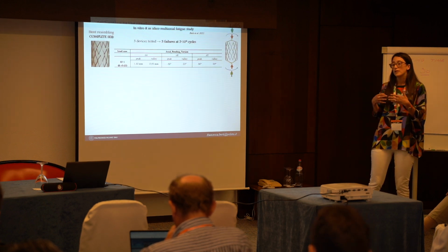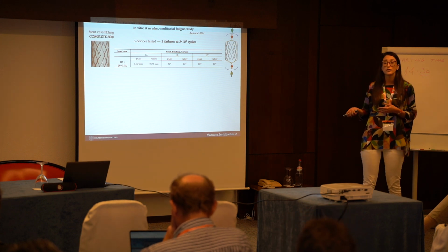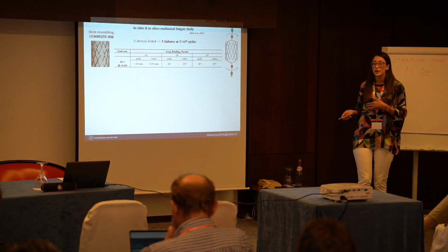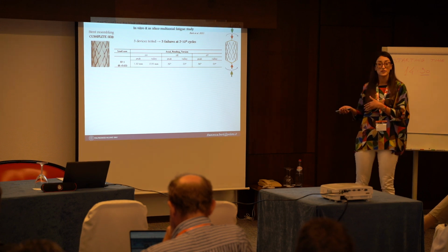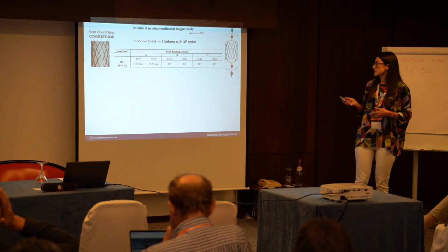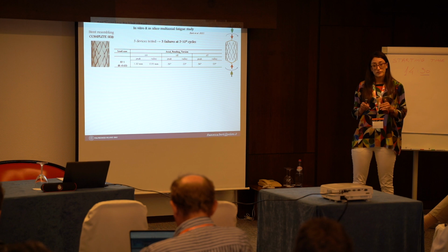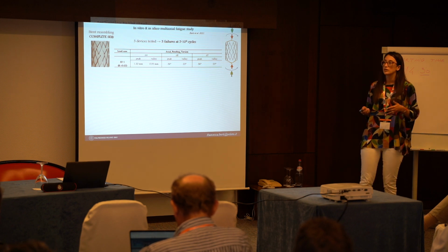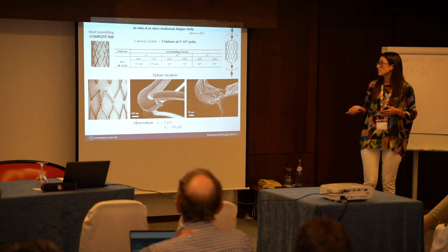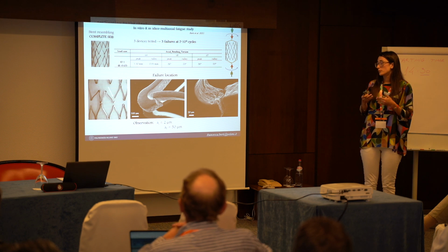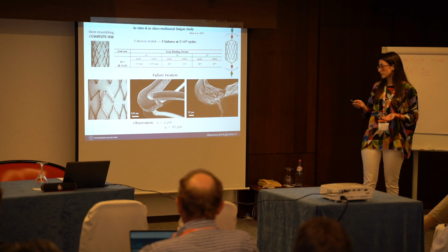However, we wanted to apply this to a more complex case, which is the one of the stents. So I performed this in vitro campaign two years ago on stents tested under multi-axial loads, and I also performed numerical simulation. In particular, at a specific load case, I tested 3 devices, and all of them broke at about 20,000 cycles, and all of them broke at the same location, as you can see. So, from the observation, we could make the hypothesis of an initial crack length of 2 microns and a final crack length of 50 microns.